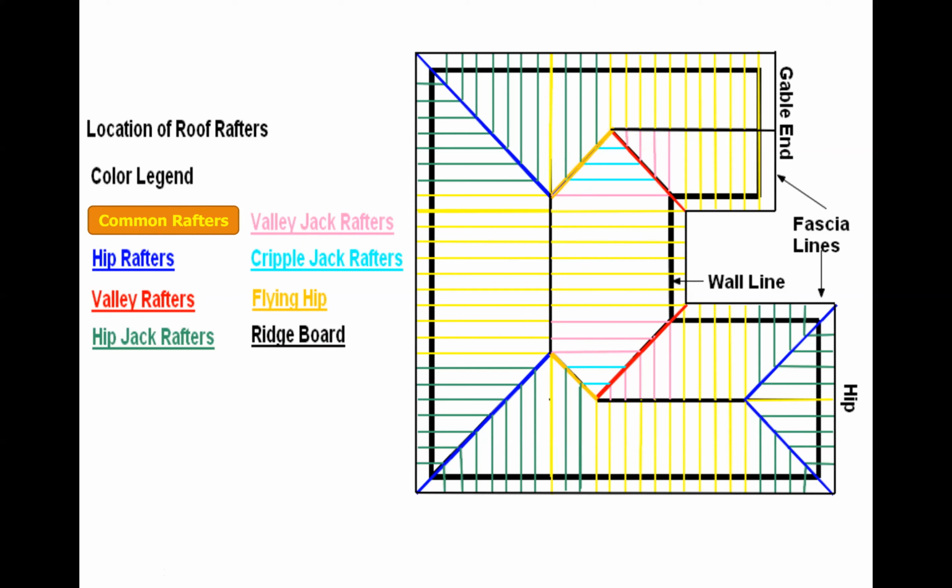And then I'm going to drop down to the lowest point of the roof, which is not listed over here, but I'll talk about it nevertheless. It's labeled over here, but it's the fascia board that goes around at the lowest point of the roof. If it's a gable end, it goes up and comes down. So this roof is a combination of hip and gable. This end here goes up following the profile of the wall, but for a hip roof, you would have all of the fascia boards horizontal, going right around the building. But for the gable end, it goes up to form like a triangle and comes back down, right? Then it goes horizontal. So the fascia board basically is at the lowest part.